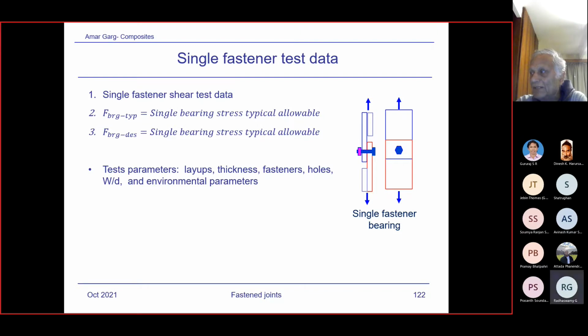And especially for the buckling, nonlinear analysis. I didn't show the chart where the buckling characteristics had to be shown, because that is even more difficult: predicting the onset of buckling from the test and matching it with the FEM. That took us several months to really validate the post-buckling behavior, comparing the results of such a large structure with a FEM. That was not a simple match.